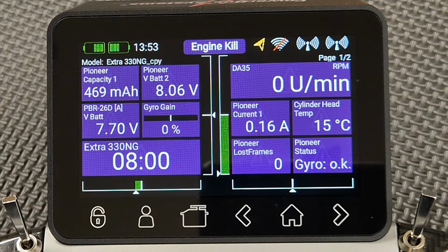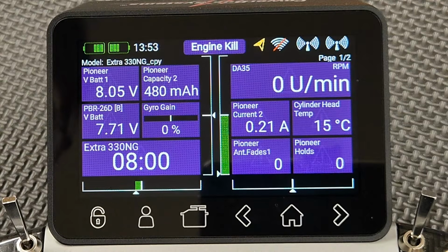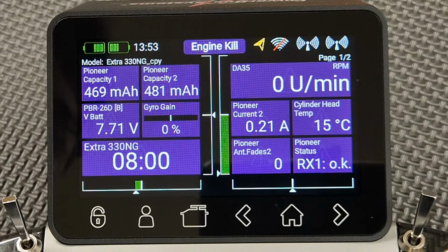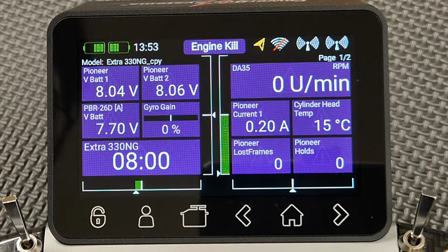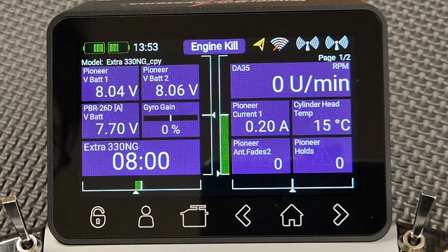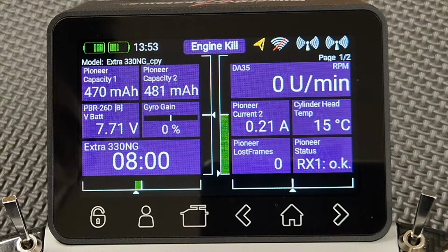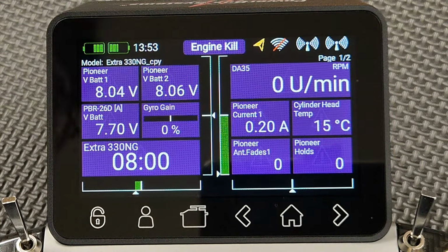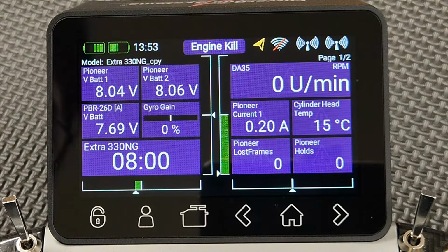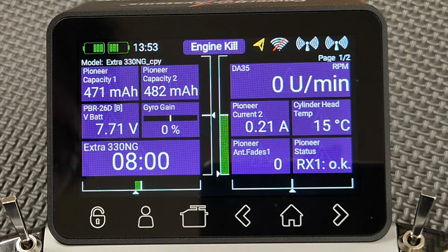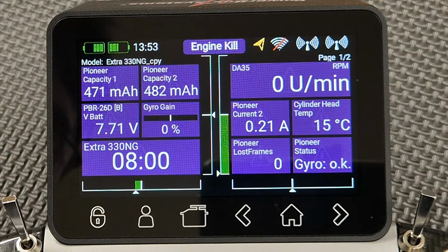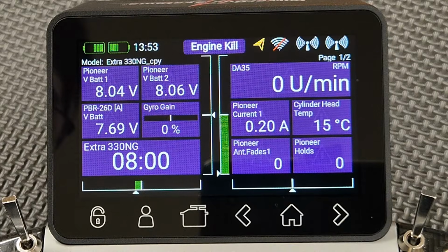So typically for an internal combustion type engine, we want to have an idea of how long it's been running for, how much work it's done, so we can then schedule various maintenance activities. So for instance, with my Saito 4-strokes, Saito recommend that every hour you have a look at the valve clearances and adjust the valves if need be. And that interval is set by the manufacturer at around 60 minutes or every hour. That'll vary a little bit depending on how much work the motor's done, because it tends to settle in after a few hours.